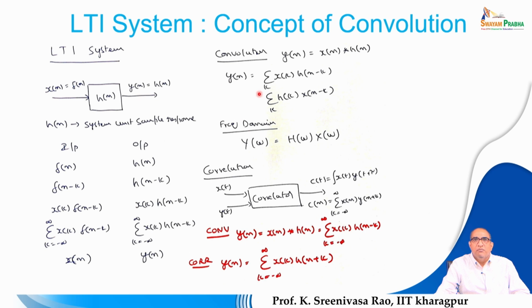And now, let us see, this is the time domain way of analyzing the LTI system. Suppose we want to analyze the LTI system in the frequency domain. In that case what we can do, because these are time domain signals, is apply a Fourier transform on this discrete time signal, and then we can come to know what the output response of the system will be. If you compute the frequency domain representation of y of n using a Fourier transform with appropriate relations, and plug in the Fourier transform expression for the input, you can observe that Y of omega is nothing but H of omega multiplied by X of omega.